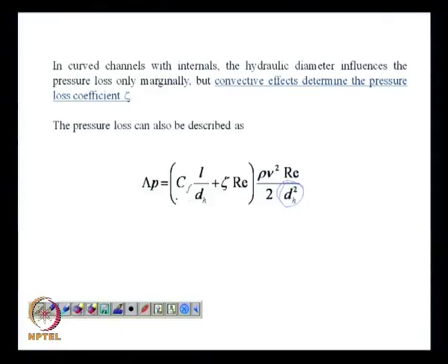Okay. So, electric field is one example, but that would give rise to interesting effects such as electrokinetic effects. What happens to the viscosity when you use an electric field to move a liquid from one side to the other? Because the electric field near the liquid-solid interface would create an ordered structure in the liquid molecules. So, the apparent viscosity of the liquid will be much more than the actual viscosity of the liquid.